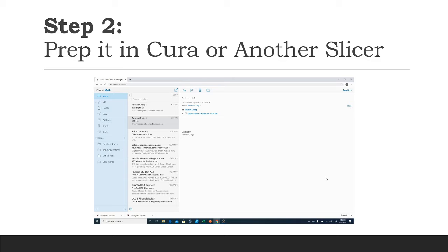And the nozzle size is the most important thing. I know that I have a 1mm nozzle put in my printer right now, so I'm going to have to change it for the 0.4mm nozzle for this print. So those things are very important to take into consideration. Now the next thing is these basic settings here. I think all of these are good.